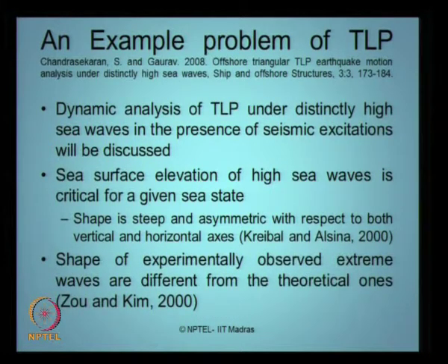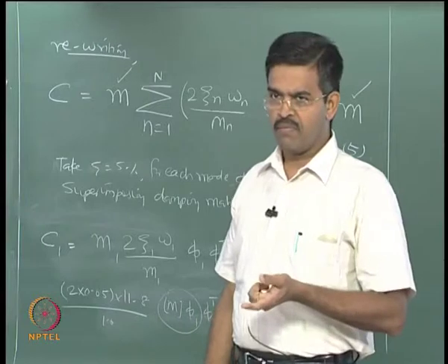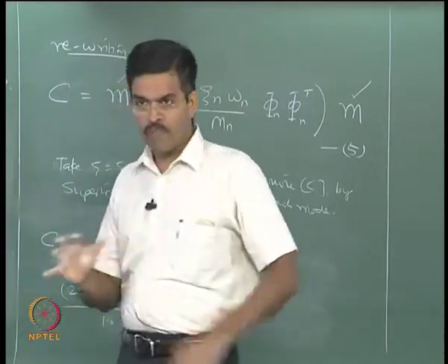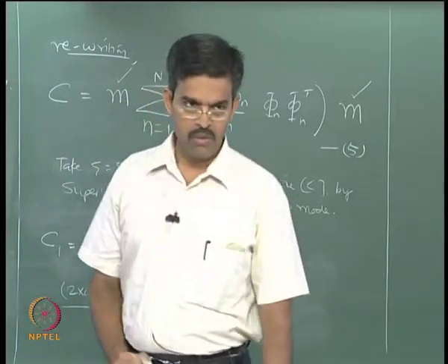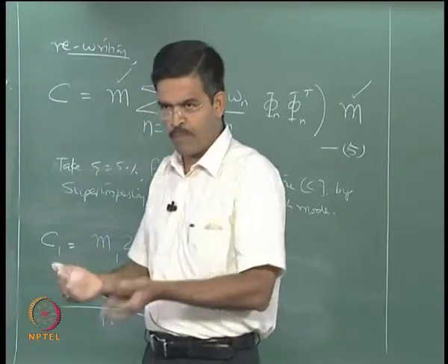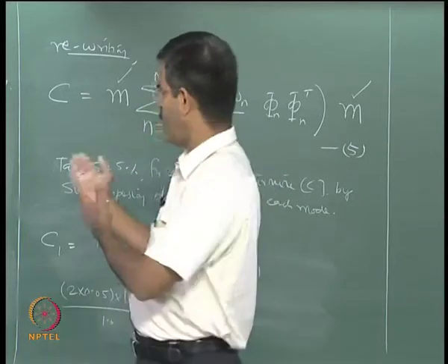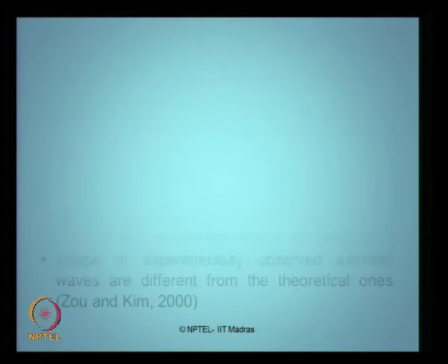The shapes of these experimentally observed extreme waves are also available, and they should be compared with the theoretical ones we are generating, because theoretically people have not generated this wave, but experimentally they have measured it. Zhou and Kim have done this, and if you generate a wave numerically for analytical investigations for this problem, this wave should match what you have in the experimental observation. Okay. So, there is a limitation within which you must develop your model, update your generation of the loading first, then apply it to the problem. The loading itself is updated with the experimental observation in this particular case.